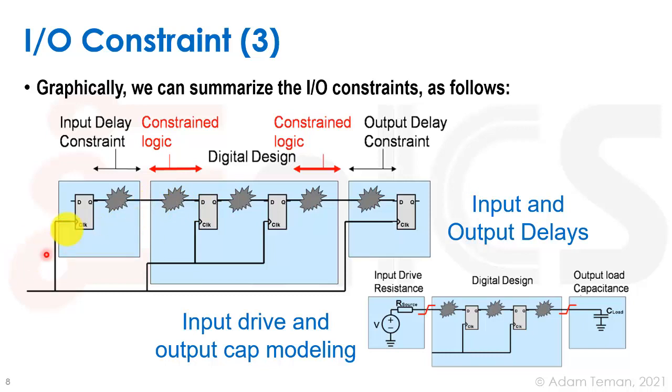By the way, when we finally tie these things together, if it's a hierarchical design, we'll see, this becomes a reg-to-reg path, and we'll be able to check the whole thing. But we want to plan for meeting timing and not having to make ECOs after we actually closed each of these hierarchical blocks. Same is done for the output.